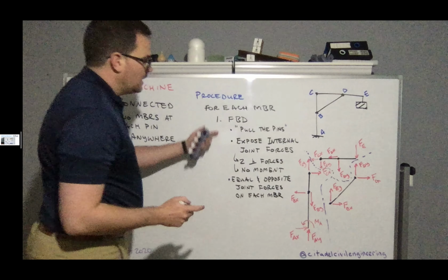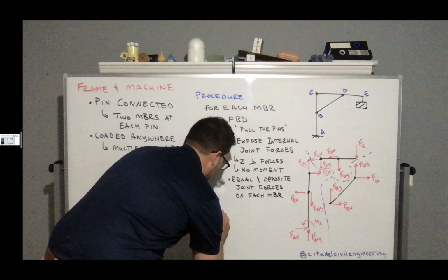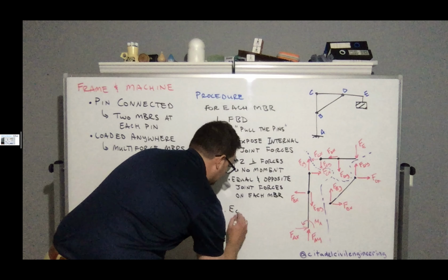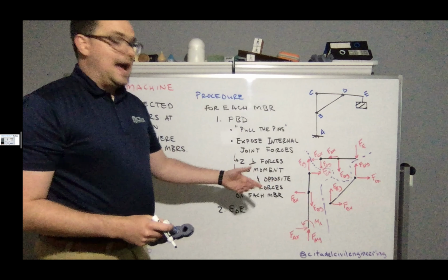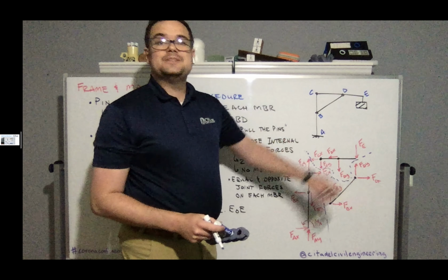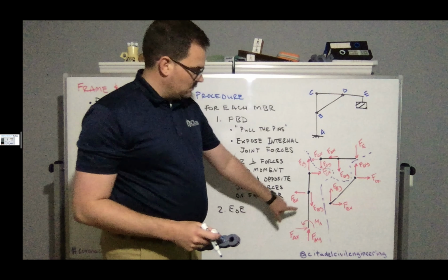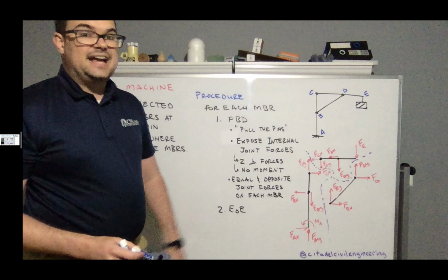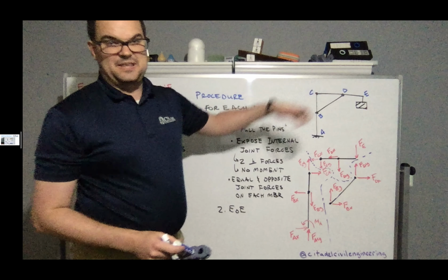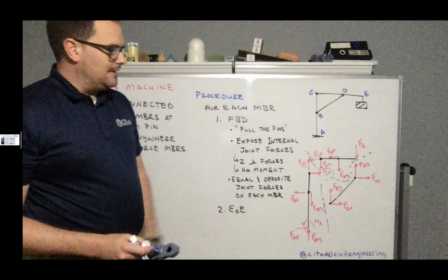So once I've done my free body diagram for each case, I can write the equations of equilibrium. Now, we won't do that for this problem right here, but I will point out that we'd have up to 9 equations, so 3, 3, and 3. In addition, we could do 1 for the big structure, but that's a little extra.